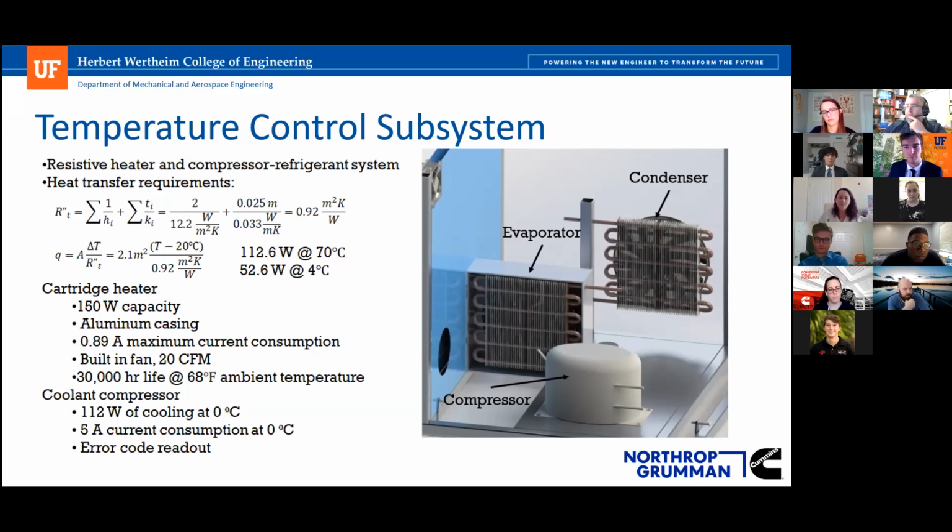As Daniel mentioned before, we are using inch-thick styrofoam, which is sandwiched on either side by 16-gauge aluminum sheet metal, but that's neglected in this analysis because its contribution to the thermal circuit is practically negligible. We then use that thermal resistance to compute the heat loss at any internal temperature.